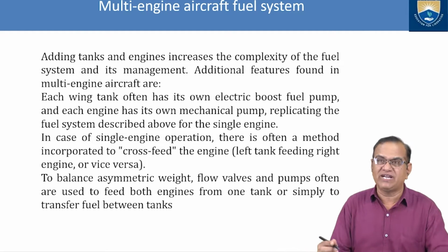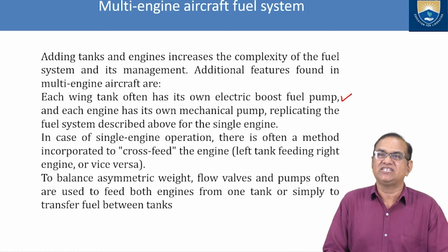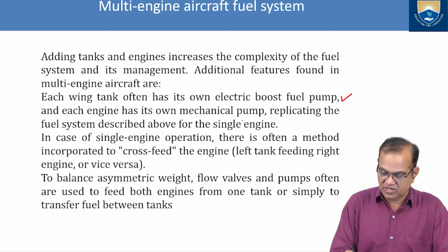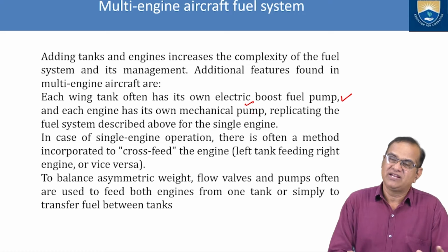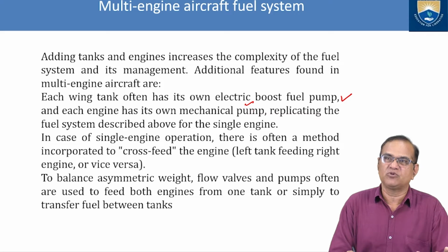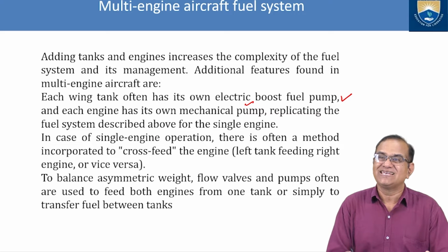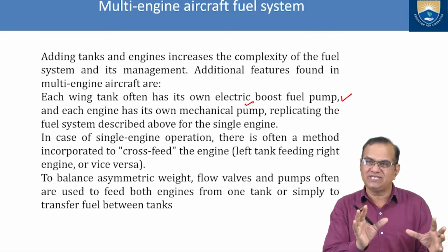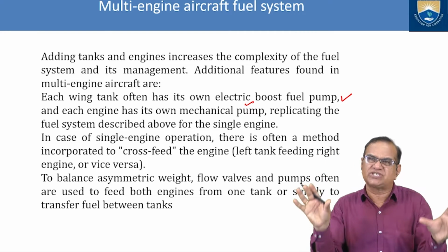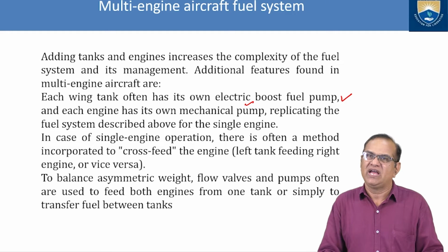So for every tank, we will have its own booster pump, and each engine has its own mechanical pump. So engine-driven pump: for every engine, there is a separate engine-driven, or mechanical, pump. For each tank, we will have a separate booster pump, replicating the fuel system described above for the single engine. So just like for a single engine, if we have 2 engines, we will have 2 systems in total. Every pump, everything for each system will be different and separate.